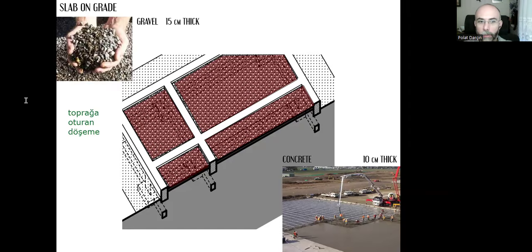And there is a reason for us to put gravel over the compressed earth. This is the upper surface of the earth, and it's compressed now. It's smooth, and as you know, earth ground is a granular porous substance that can include different grain sizes. The bigger one is called gravel, the smaller is the sand, and then there's silt and clay, four different grain sizes. And why do we need 15 centimeter thick gravel over this mixture of different grain sizes? There's a reason for that.